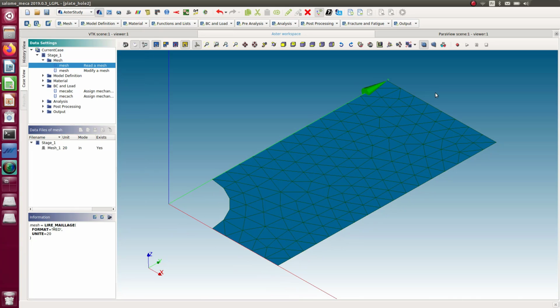So I'm going to talk briefly to explain how this works, because a lot of you probably don't understand this, even if it is very basic stuff. You saw how I assigned the pressure to this load. Because this is a pressure load, I used this function press rep, which basically means pressure distribution. It means that I am applying a pressure distribution to a certain geometrical shape. So I'm putting 100 Newton per millimeter on this edge.